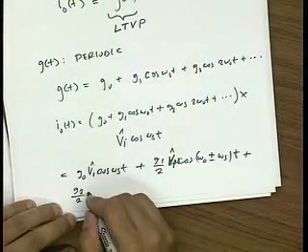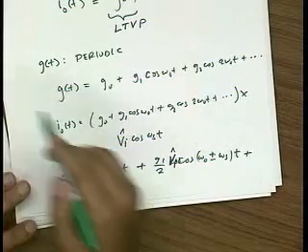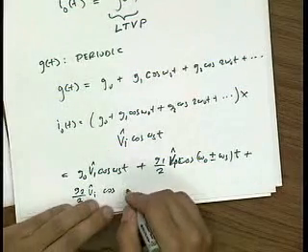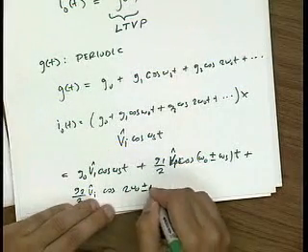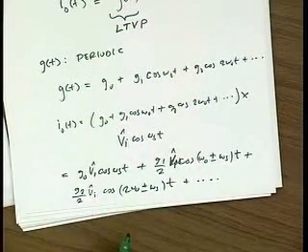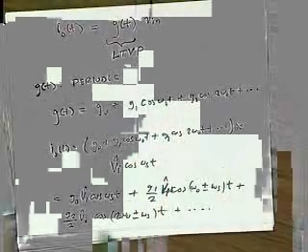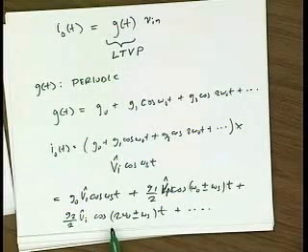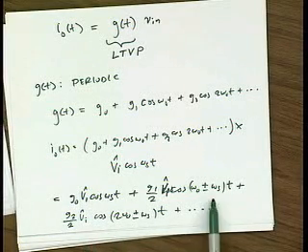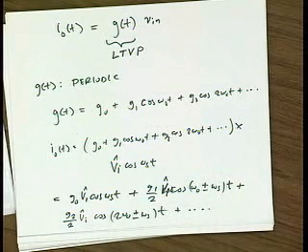And then G2 times the input gives us cosine of 2 omega naught plus or minus omega s, t, and so on and so forth. So we can see that a linear time-varying periodic circuit is a mixer that generates lots of products. And in theory, we could just filter the circuit and pick off the desired product and ignore all the other products that are generated.